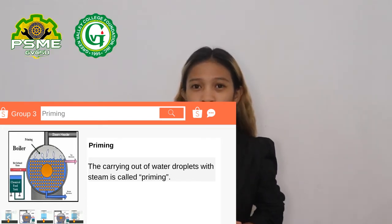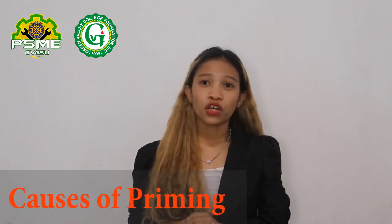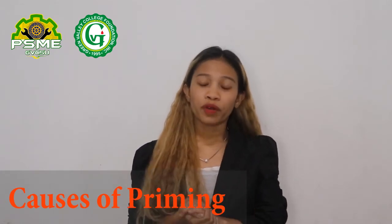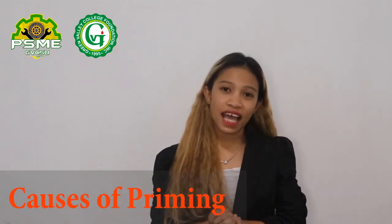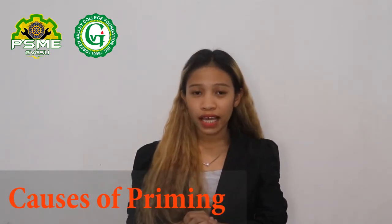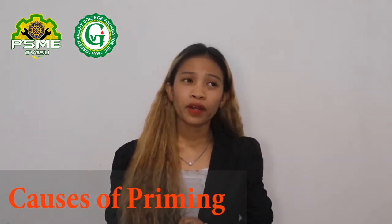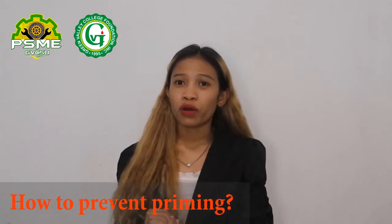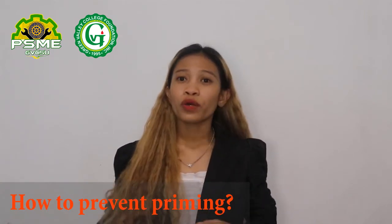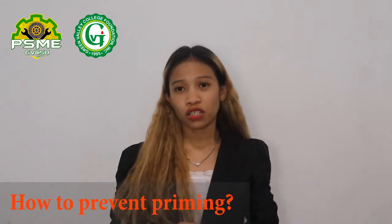What are the causes of priming? Due to the presence of a high concentration of dissolved salt in the boiler water, priming can occur. Next, due to a high level of feed water, priming can be formed. Priming can occur if the speed of steam generation is very high. And lastly, due to faulty or improper design of the boilers, priming can be formed. Let's talk about how we can prevent priming. Priming can be prevented if we use soft and filtered water. If the water doesn't contain any kind of impurities, we can prevent the formation of priming. And by maintaining a low level of water in the boiler, we can also prevent priming.